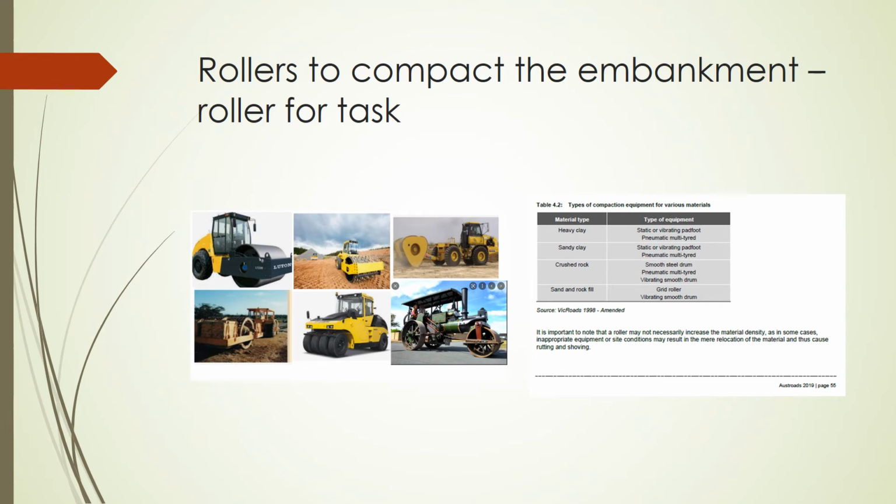The steam roller at the bottom is of course predominantly used by hipsters and vintage machinery enthusiasts. I'll let you think about whether we want to use that here at the Shire Council. Now, the degraded granites of the Moira mine are estimated to behave similarly to a sandy gravelly clay. Thus, we're expecting that smooth drums and vibrating drums will be needed for the select material zone under the base.